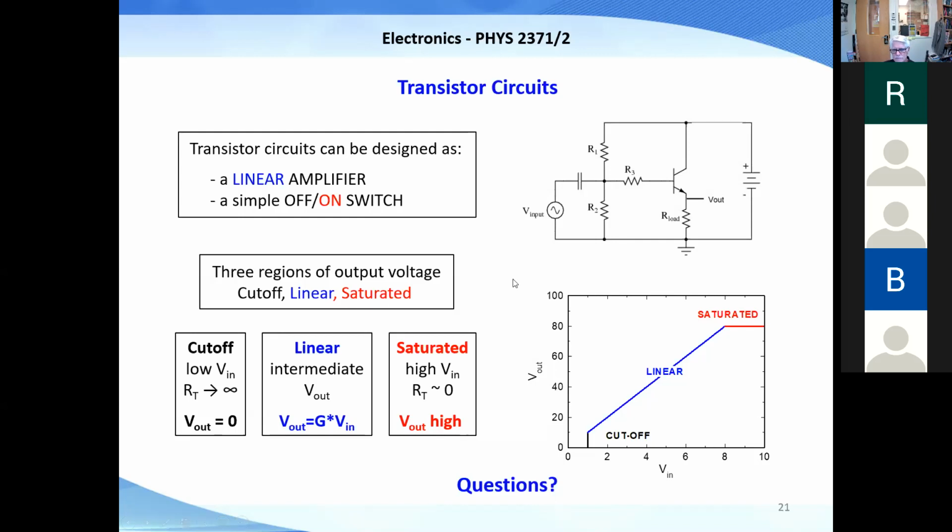Okay, so you have 1 volt go in or whatever, and then 10 volts potential come out. Right. Depends on what resistor you use here and what resistor you use here. In the experiment this week, you're not going to get much gain out of it. Okay. We just didn't design it that way. You get a little bit of gain, but we're not interested in getting high power out to drive anything. The circuit is just to look at this plot here.